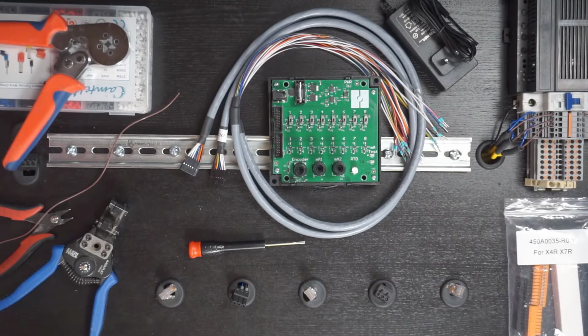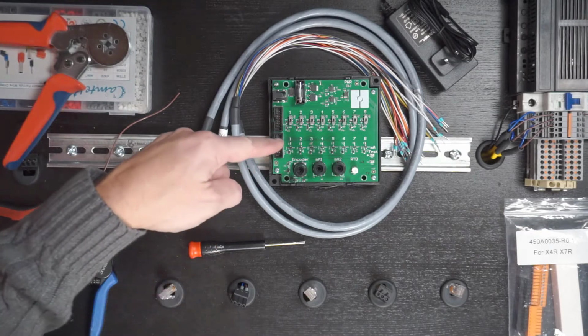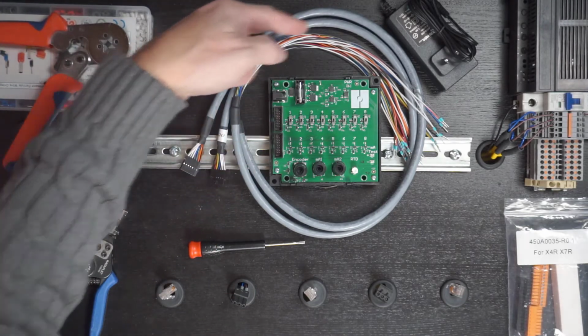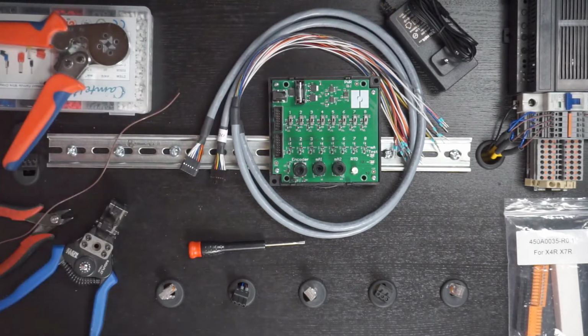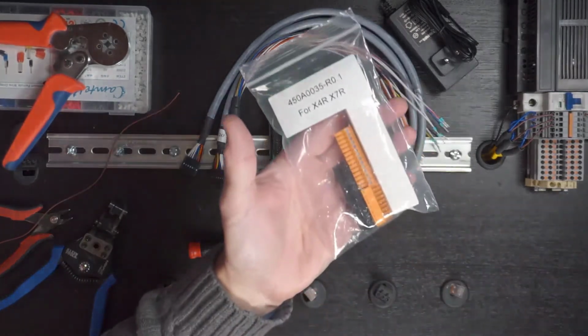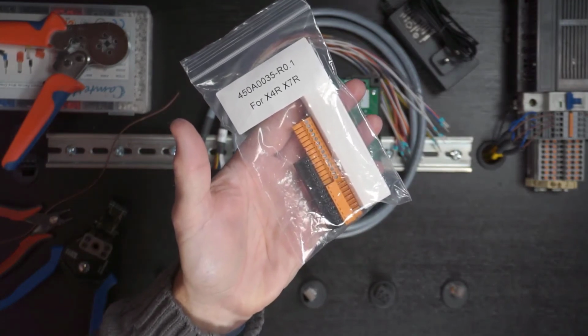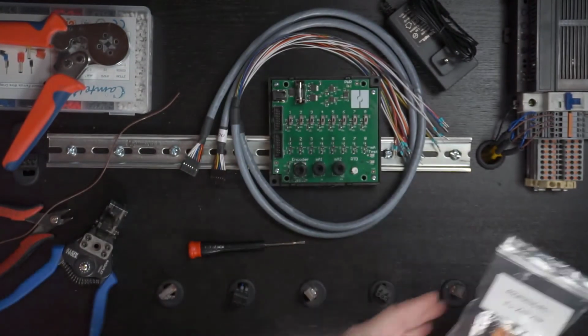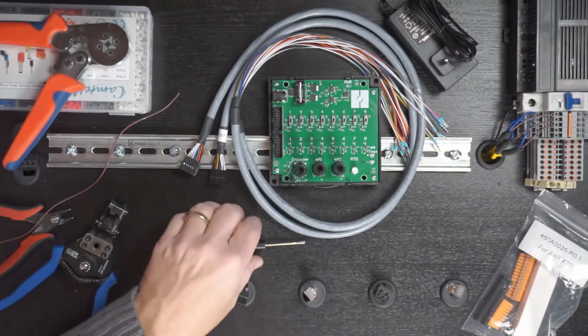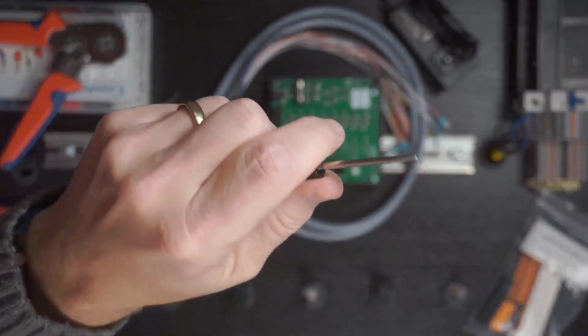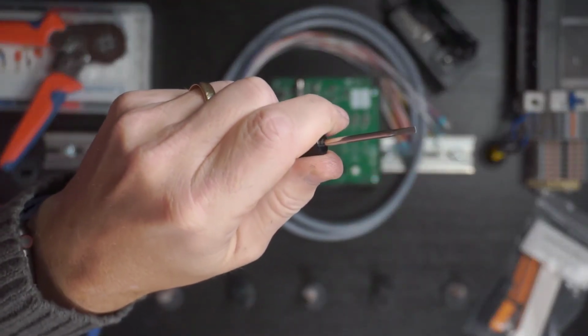Okay, let's take a look at all the things we might need if we're going to connect up this I/O simulator. Of course, you're going to start with the simulator itself, along with the cables and the power supply that both came in the box with the simulator. Of course, you're going to need the I/O terminals and the power terminal that were included with the Micro OCS or whatever OCS you're going to wire it up with. And other than this flat-bladed screwdriver, a fairly small one, not tiny, but fairly small, that could be all you need.